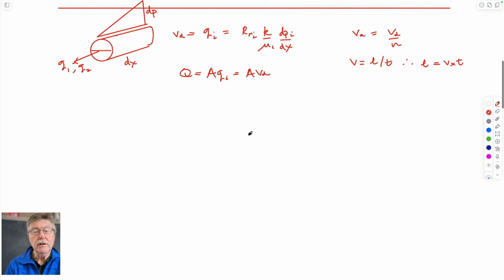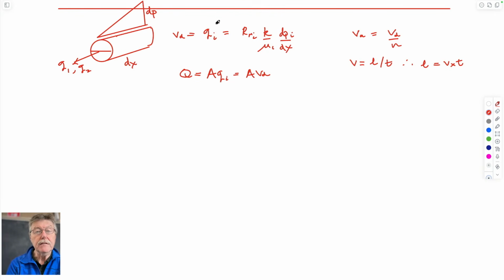And so from Darcy's law, we can get a flux. If we know things like how the water table is sloped and what the permeability is and what the fluid that's flowing is, we can get the Darcy velocity, and from it the advective velocity. If we have the advective velocity, we can make a picture that we've had before for length traveled in a given time.